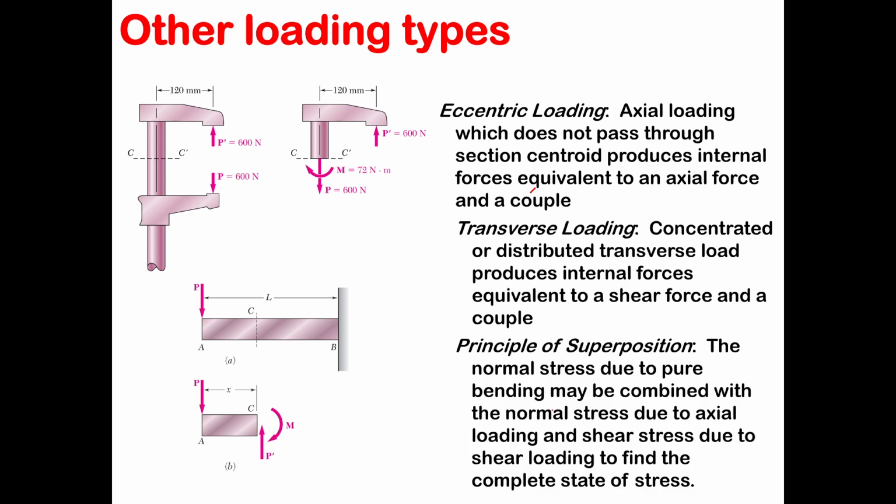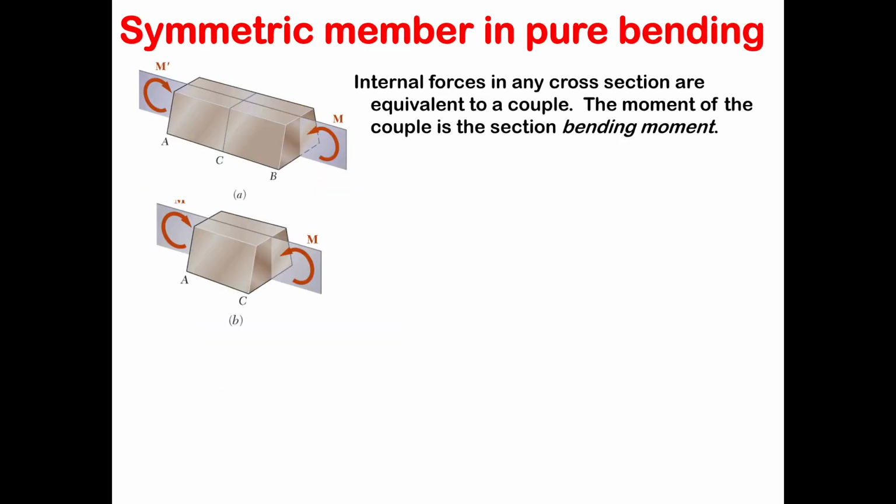What does it mean? It means that you can essentially analyze the moments first and then analyze the forces second, do a bending analysis, and then do a tensile analysis or whatever, a tension analysis, right? And just add the two together eventually to get the final result. And we're going to see the examples of this later on, right?